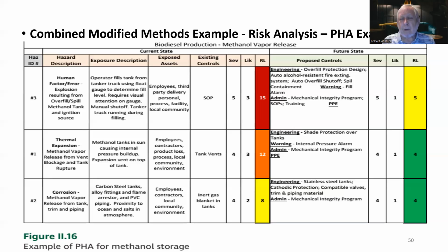Usually your Department of Labor in your state has a boiler inspector or a chief boiler inspector, and they frequently farm that out to insurance companies, because the insurance companies have a dog in that fight, and they have licensed, certified boiler inspectors. They come around and check all your pressure vessels, not just your boilers: your air compressors of a certain size, CO2 tanks, any kind of tanks. Under a certain size they don't, but one of the things they check, and believe me, they check it, is your vent.